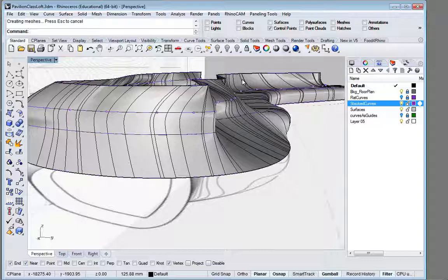So it's generally the case that when you get those two things, you just want to keep those top and bottom pieces where they're at, and then edit the ones above it. So you might have that bottom curve, and then you have one just above it that allows you to control that tangency between the two surfaces. Does everyone know what I mean by tangency?